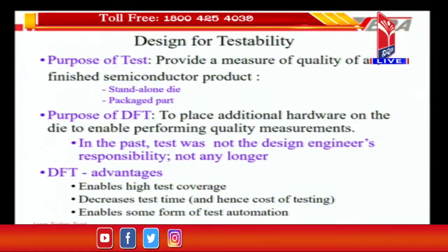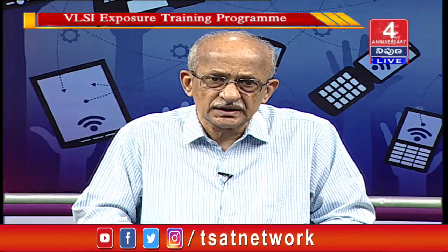They read in the netlist, they get the connectivity information, and based on this connectivity information they will generate the patterns. Okay. Not only will they generate the patterns, but for every pattern that has been generated, they will also know what is the output response for a perfectly manufactured circuit.